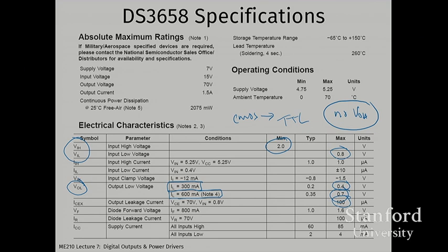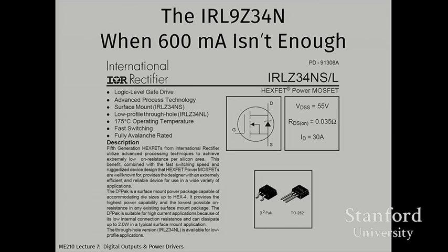So these are the specs. If we're thinking from the standpoint of logic devices, we've got our VIH, VIL, IOH, IOL, IIH, IIL. We've got a VOL and an IOL, but no specs for the output high state. That's what we normally expect for open collectors.